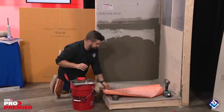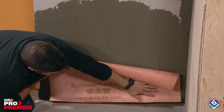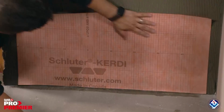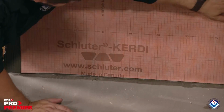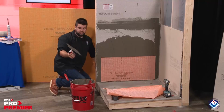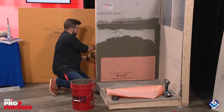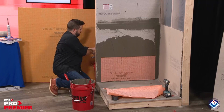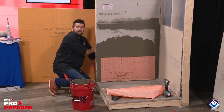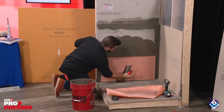All right, we're ready for our first piece of membrane. I'm just going to align this with the bottom. I've got it up there. I'm going to actually take a sponge and clean this trowel off. Something else that works great for what I'm getting ready to do would be a broad knife or a flat trowel, a drywall trowel, something along those lines.